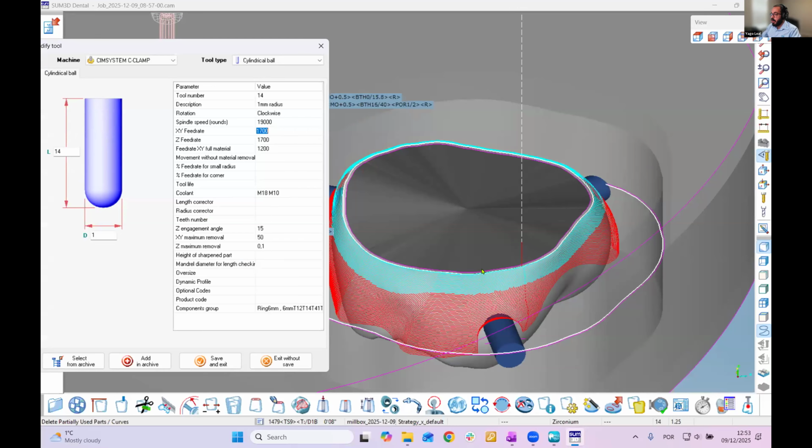So it's like less than a third of the speed. But you don't need to do that. You can keep your original one and just set here, because this means that you're going slower when you're close to the margin line, and then faster on the external areas, which usually don't have chipping problems, right? So you can do something like that here.